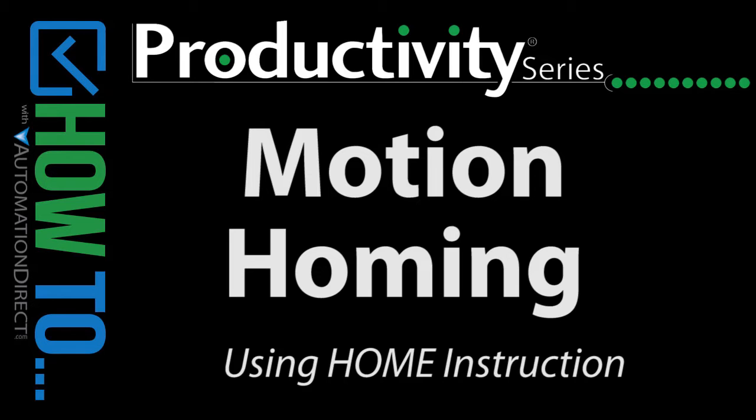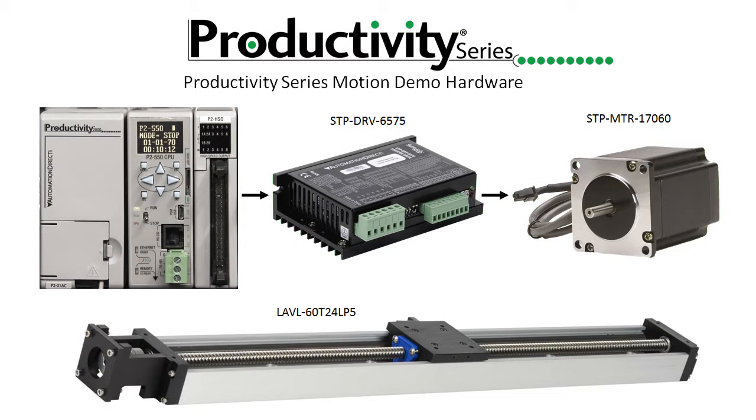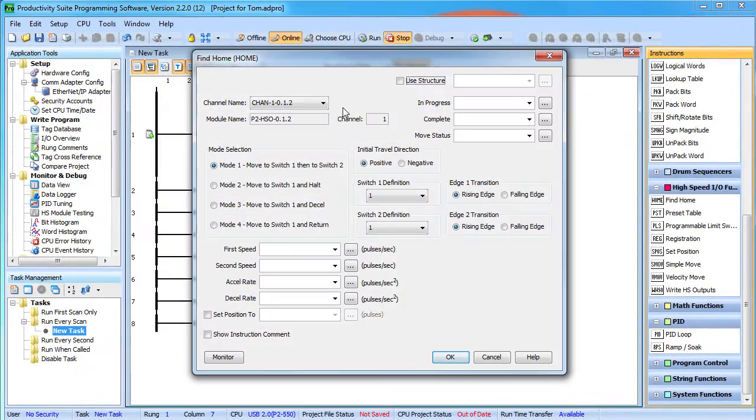The home instruction gives you a convenient way to locate and set your home position. We'll use the same linear slide configuration that we used in the simple move video, so check that out to see how we set all this up. The only difference is I added a third limit switch to one end so we can test all of the homing modes. Let's bring up the home instruction, select the channel we want to use, and create a structure for